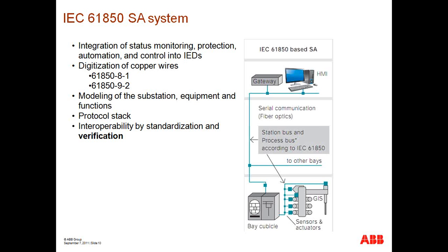That is rapid exchange of information between IEDs inside of the control house. Another component of the station bus is the exchange of information from each IED over to a gateway or a data concentrator inside of the substation. So it is referred to as the station bus because this is a network that's usually within the substation or within the control house building.